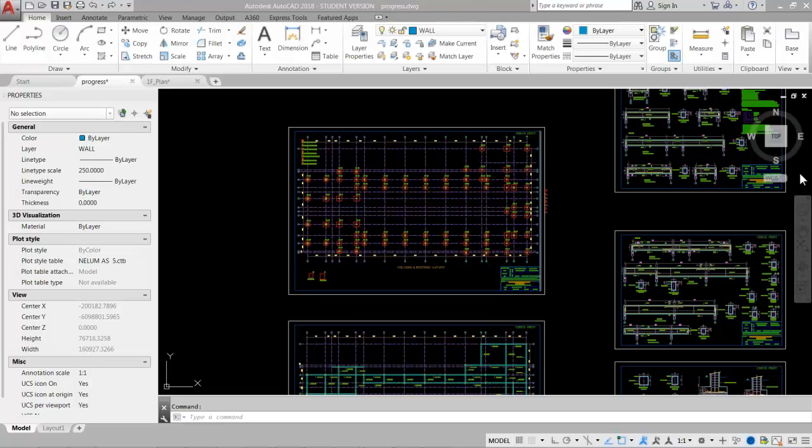We are done with the analysis results that we can check. And we were going to go ahead and look at the tables. In the tables we can see the rebars in beams. So let's see all of them. Okay, seems like the design was not performed. Let me perform the design of this structure again because of the crashing. So we'll run the design.